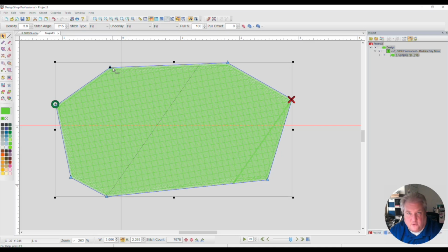down. Now, if you're a keyboard person, hold your shift key on your keyboard and your up arrow, your four arrows, and you can actually move it by ones. Then shift alt is tens, and then shift control is hundreds, if you care for that.